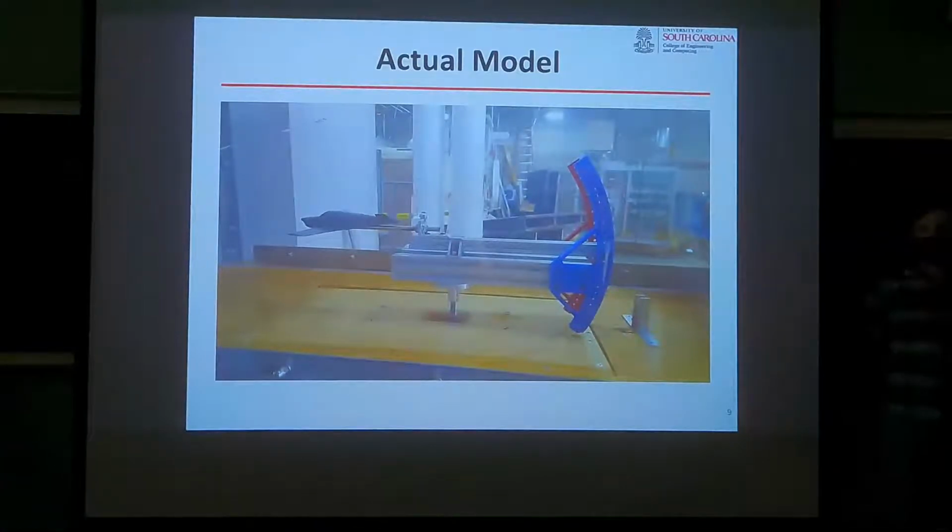Okay, go ahead. I guess I'm gonna start from there. So, understanding of this experiment. You're gonna have to speak out loud. My understanding of this experiment is that you were essentially getting validation for the different angles of attack on a known shape, like a known aircraft. Yes. Okay, so based on that, from what I understand about the experiment, this would be a mechanism somewhere in the fuselage itself that would change the angle of attack based on the conditions the airplane is in. It's actually under the fuselage.